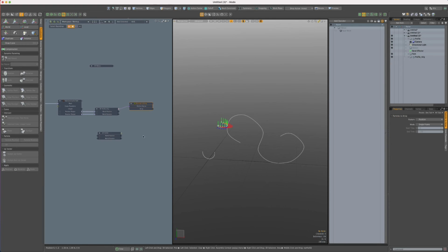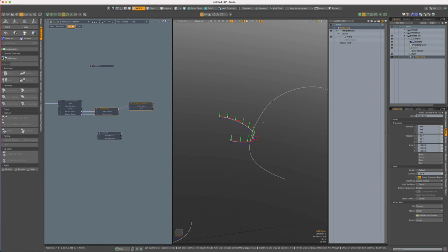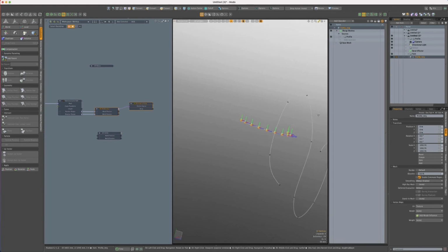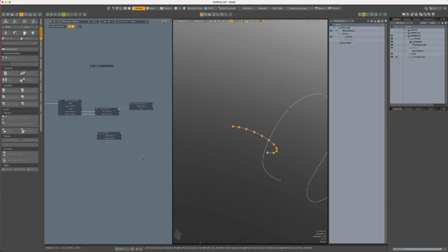And if you select the particles to array, it's going to show you a preview of the positions for each of your array points. You can see that the feature is using position. And if I select the profile merge, it's creating a position at each of the vert points. What this means is you could change your resolution by changing the number of points along here, which we can do procedurally in a number of ways. I'll show you one of them.